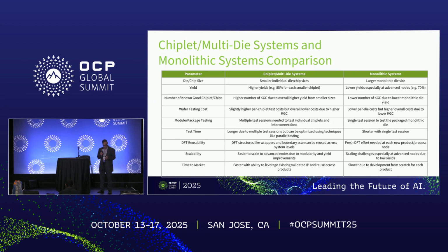and more test time is going to directly, proportionally increase the cost of your package. And one thing I would like to emphasize here is when you are building chiplets, not for monolithic application, but for system integration, it is desired that you stress that chiplet much more than a regular die, which is going to be packaged as a single package. The reason is thermal variation, power noise, and other factors. Because a single die, when packaged in a single package, is going to go through a very, very different system stress when it goes on a PCB.